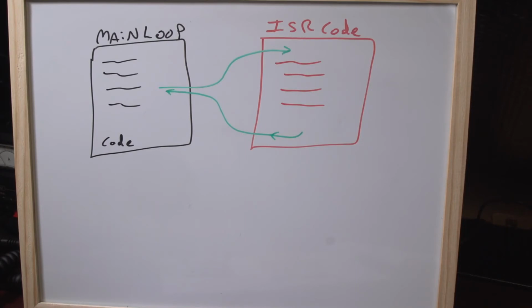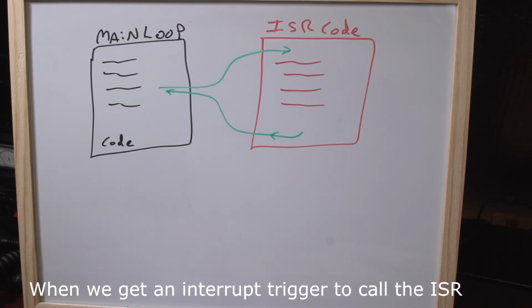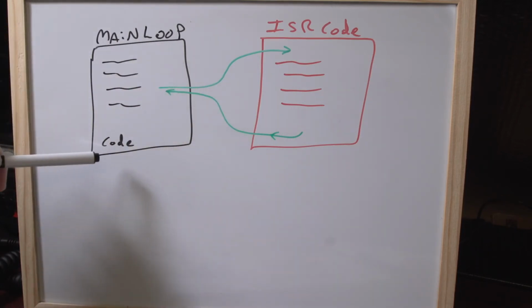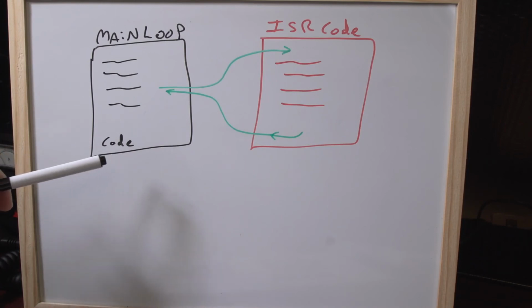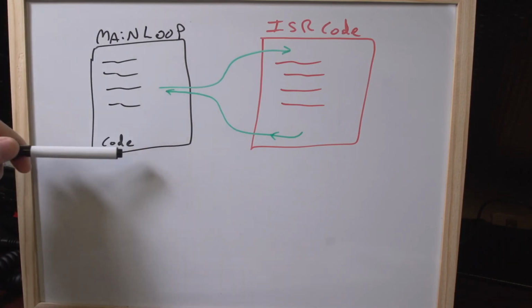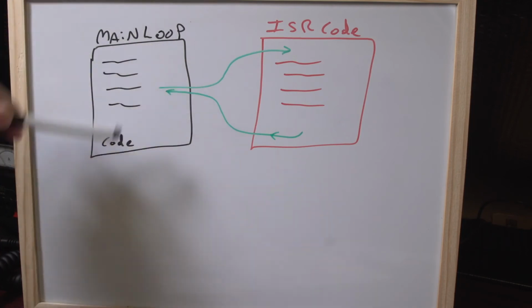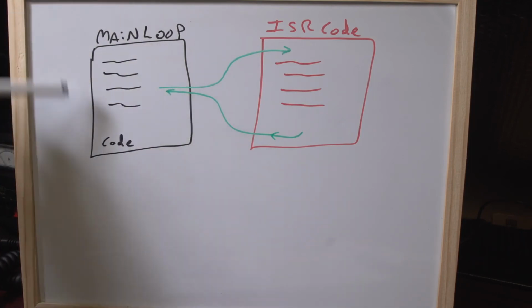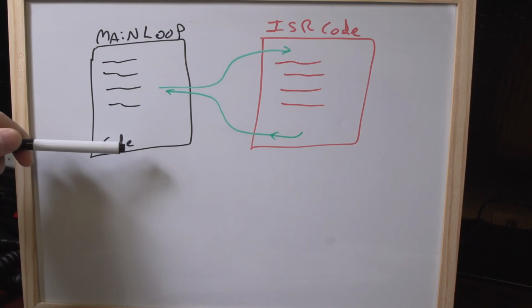And here I'd like to explain a little bit about what's happening when we call the interrupt. When we receive the correct logic state on the interrupt pin, that's pin 2 if you remember, what actually happens. Okay, so this is our main code here, and in our case we're running a continuous loop in the Arduino code, in the source code. So we're running through our instructions, then when we come out the bottom we start again. So this is our main loop, turning the LED on, turning the LED off. So this is our software code here.